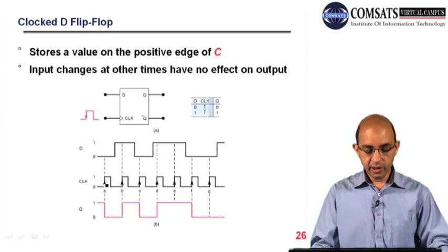This is the rising edge. So D, clock and Q bar. Q is 1 when we have started, and then on the active or rising edge, Q has to follow D. D is low, so it will go low, and it will remain low till the next rising edge. You can see Q remained low till the next rising edge. Here D is high, and we moved here.